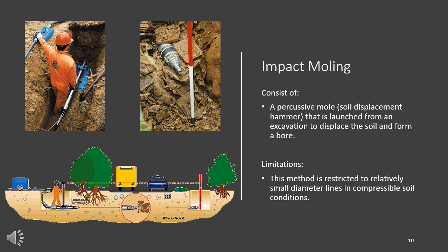Now, some of the limitations of this technology is that this method is strictly restricted to relatively small diameter lines in compressible soil conditions. So it has to meet these qualifications.